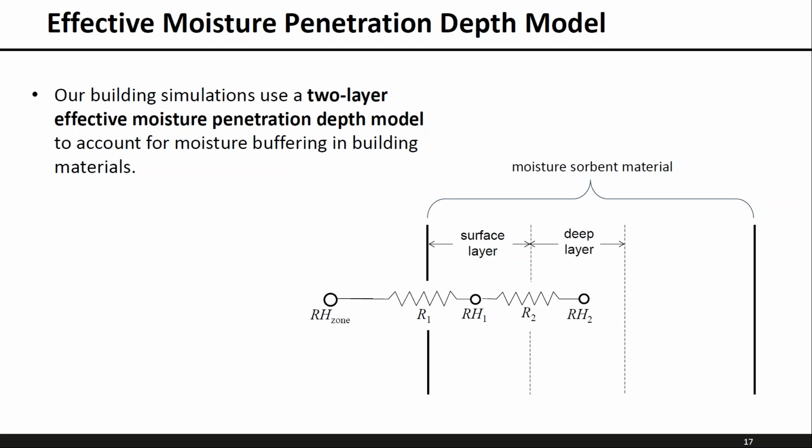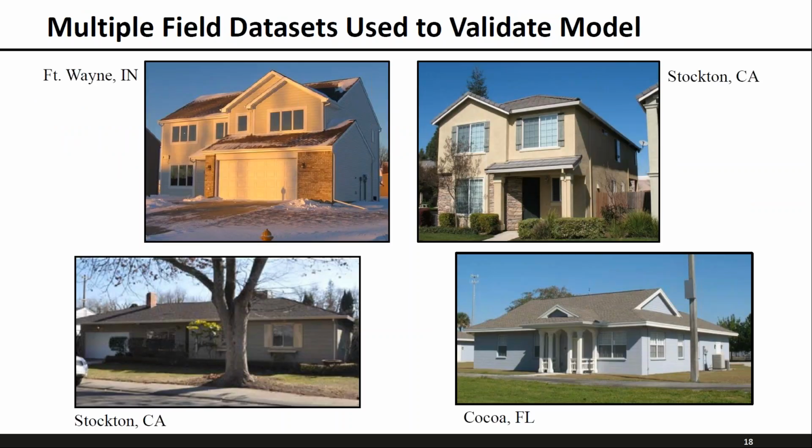And this model was implemented into EnergyPlus. It's not a model we invented, but borrowed from someone else that had developed and implemented it into EnergyPlus. It's a model that allows you to not have to do the detailed finite difference approach that had been used before, but solves much more quickly as long as you give it a good set of inputs.